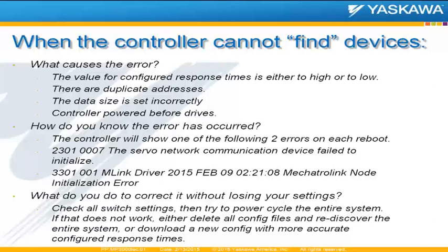And what do you do to correct it without losing your settings? Well, the first is to check all your switch settings, check your cabling, and then try and power cycle the entire system. Again, if that doesn't work, then you either have to delete all the config files and rediscover the system, or download the new config with accurate response times.